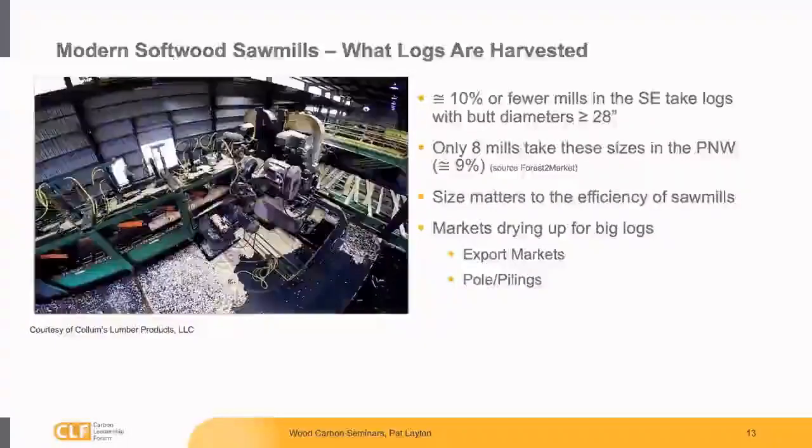And the picture you see here is the interior of a local South Carolina-based sawmill. Because we have a lot of crook in wood, we have developed saws that will actually curve with the tree so that it gives you no slope of grain or less slope of grain and gets you a piece of wood that's cut out of the log that will be best and most efficient and strongest.